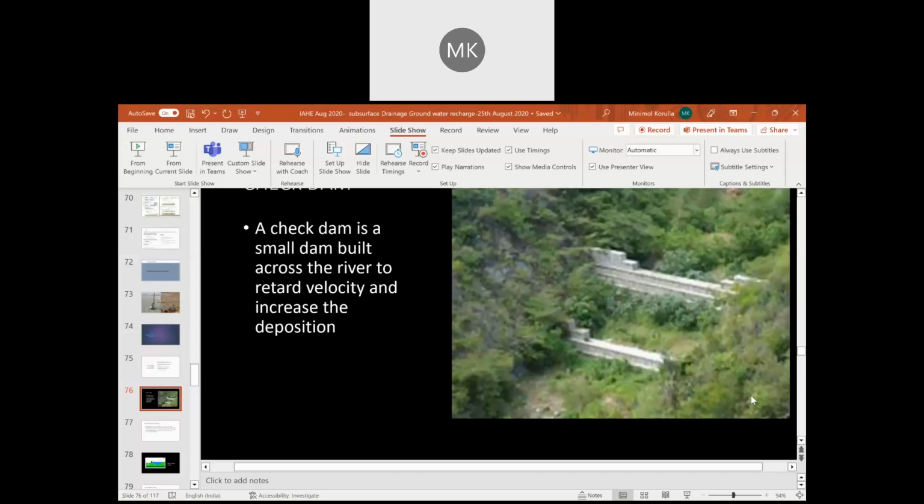So overlapping is important. Again, the advantage of going for drainage geocomposite is there is no requirement of big lapping joints or welding or anything. You can just overlap, and that also not a great length. If the soil is coming over it, or pavement layers are coming over it, simple 100 mm will be okay. In some special cases, we may have to go for 300 mm. If you can tailor it, you can still reduce it.